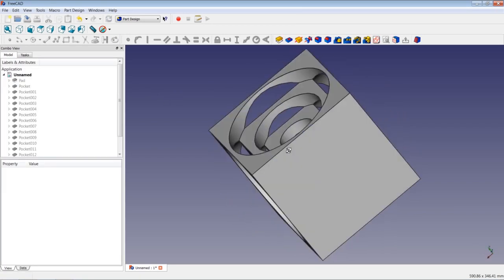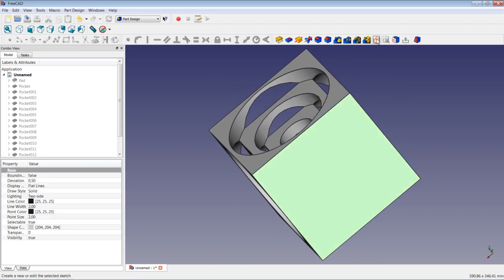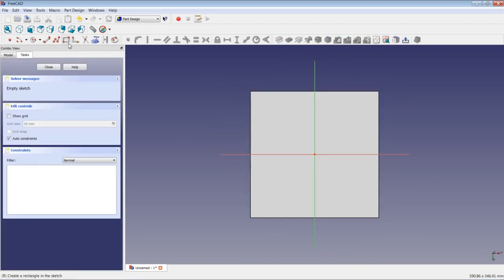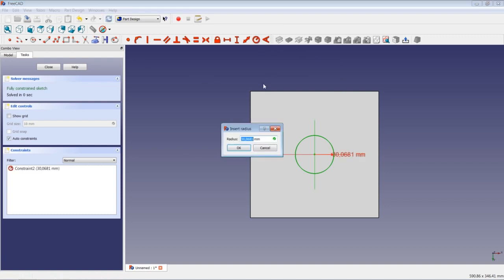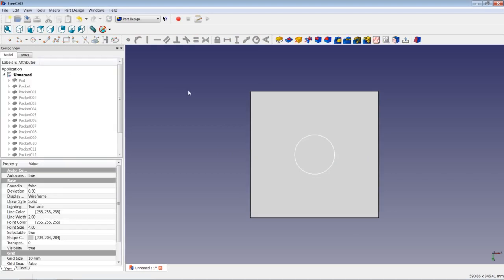And that's it. Now for the last face, we call up the sketcher, say pocket. Here we will have 31.25. Oh, excuse me for saying point and meaning comma.